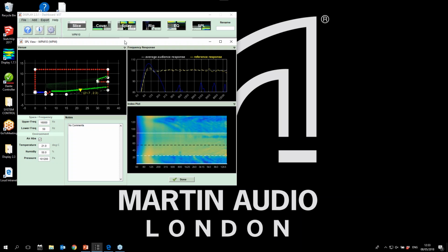So what we can see immediately in the top right is the consistency of the SPL and the frequency response through the slice, with our audience average response shown in white, the reference response in yellow, and as I've previously mentioned, when we cursor through the index plot, we can see this blue line will change from blue to red to green depending on which surface we are looking at.